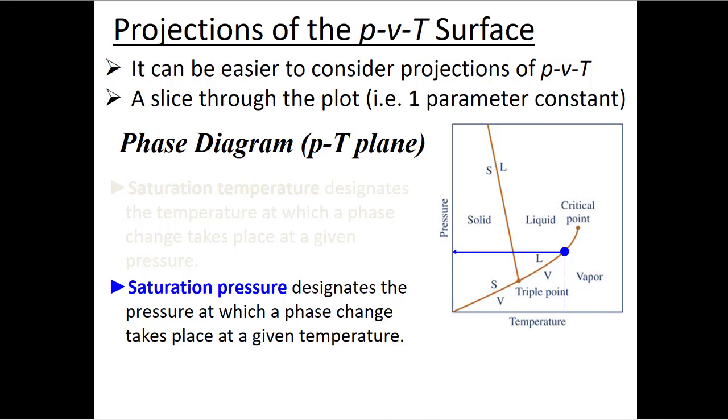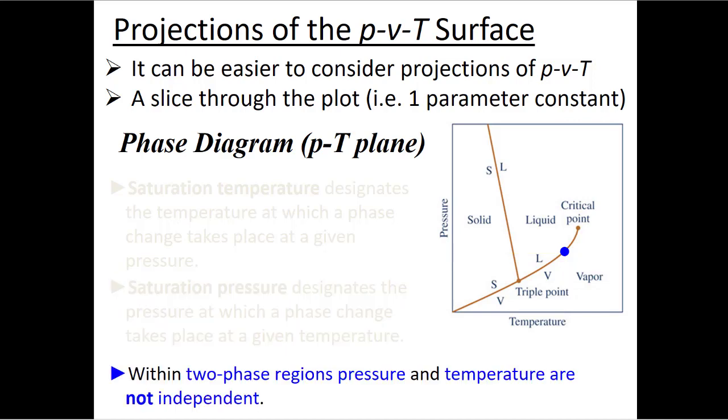You seal in your system, and as you start to boil that water, which is boiling at a temperature lower than 100 degrees, you're increasing the pressure in the system. And as you increase the pressure, it's forcing those liquid molecules closer and closer together, which means it's harder for those liquid molecules to separate into vapor. So as we increase the pressure, we also increase the saturation temperature, which you see on this graph as well.